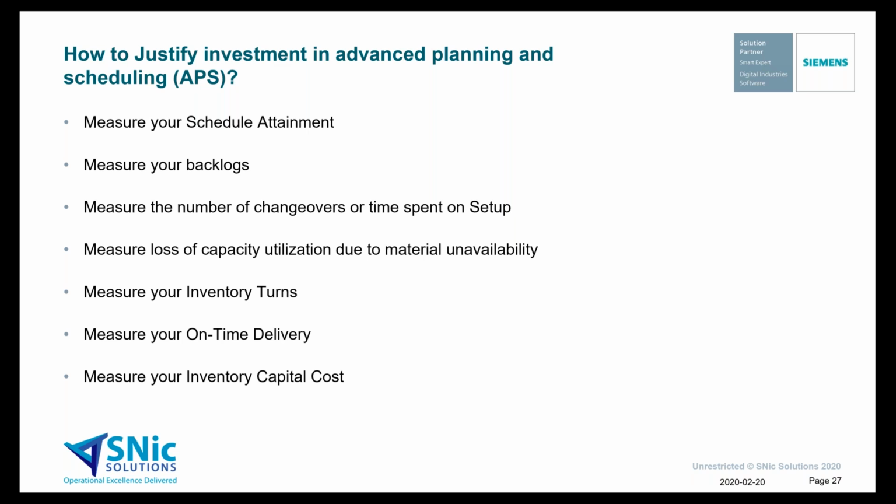If you're a company which has a lot of production variants, where you have to do a lot of changeovers, a lot of time on setup. For example, aerospace has first article inspections, or so many product variants where you need to change the toolings and the fixtures, and that results in a lot of changeover times. If you talk about pharmaceuticals or chemicals, let's say if there is a color that is changing in the product, or just cleaning that has to be done after every different batch run, you will see that a lot of the changeovers that keep the equipment idle would be a big factor in terms of capacity utilization.